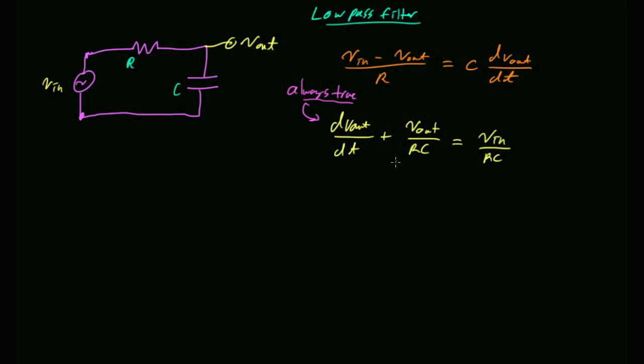So, for example, you learned that if your input voltage is a step, then your output voltage is what? Exponential. Exactly. You get one of these exponential curves where it goes like that. And you can derive the equation for that response by solving the differential equation. I'm not going to do it because you should know that by now. When you do this, what sets the speed of how fast it rises? RC. So there's an RC time constant, and if you want it to climb faster, do you need a bigger time constant or a smaller time constant? Good. So smaller tau equals faster response.